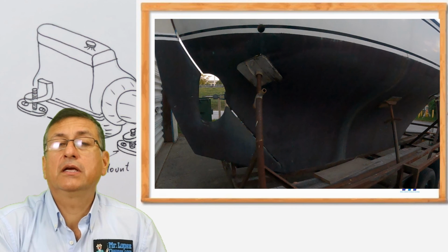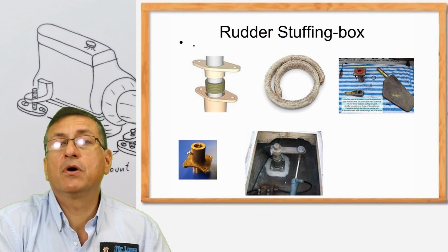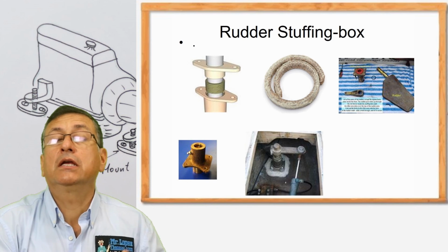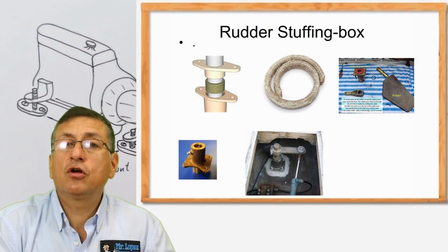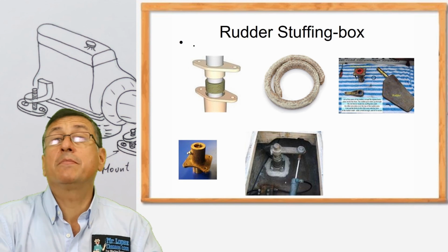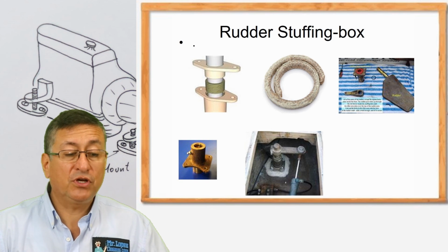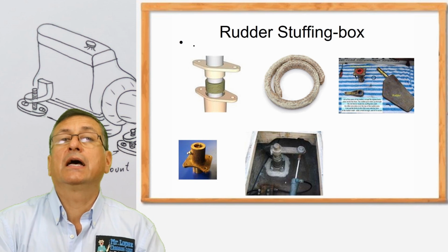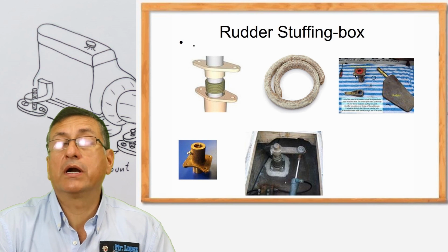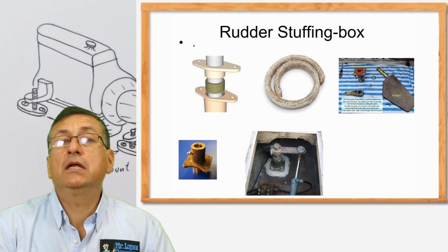The rudder, in the shaft of the rudder, uses the same stuffing box, exactly the same stuffing box used in the propulsion system on the shaft. Normally, the stuffing box located on the shaft of the rudder is the mechanical stuffing box with the seal packets that I explained to you, the procedure to replace that package.